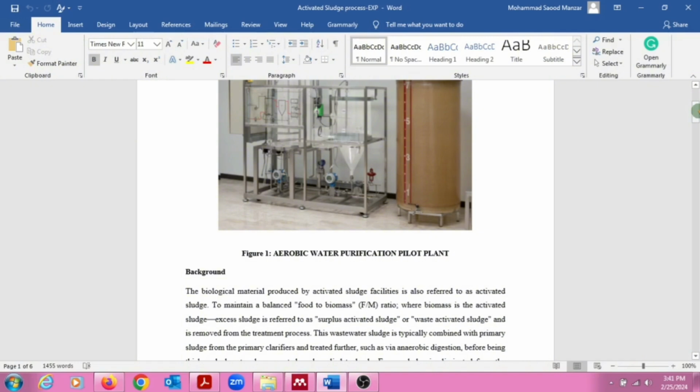So as a conclusion, we can say that the raw sewage contaminated by organic substance with limited concentration, generally not over 0.3 to 1 gram per liter of COD or BOD5, is sent to the activated sludge system, and a sludge solution concentrated in organic substance is extracted from the septic tank, that is around 5 to 30 gram per liter, and this must be treated further before being sent to the final clarifier, or the secondary clarifier.